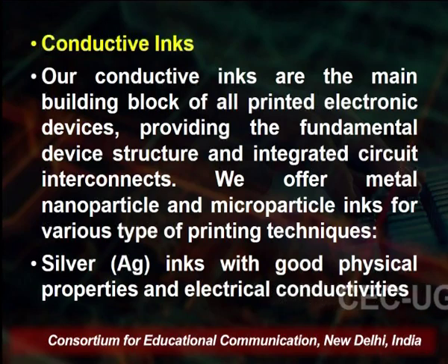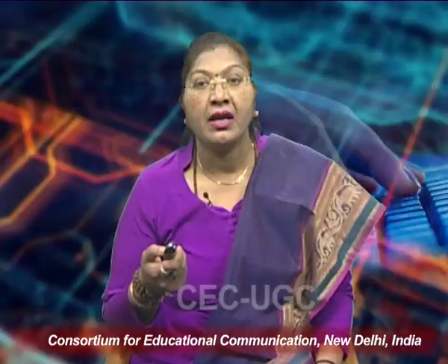Conductive ink offers metal nanoparticle and microparticle inks for various types of printing techniques, in which we have silver ink, that is Ag ink, with good physical properties and electrical conductivity. Physical properties we have already discussed, that it must have a good surface tension and a good density, and these parameters we keep in mind.